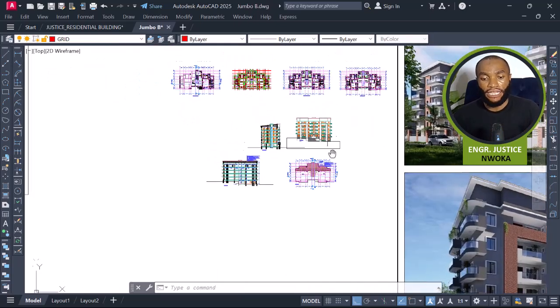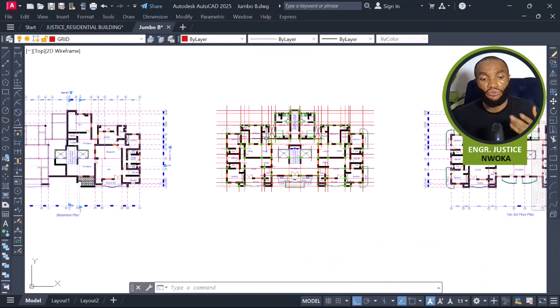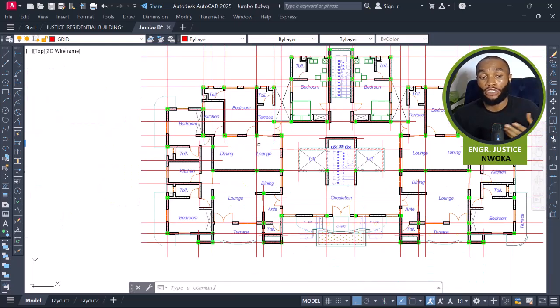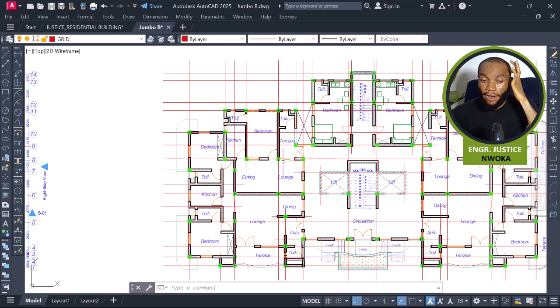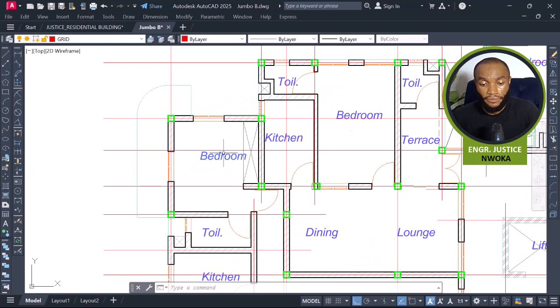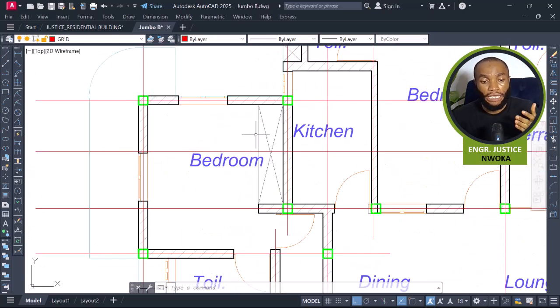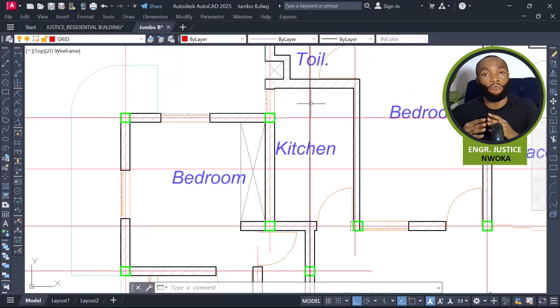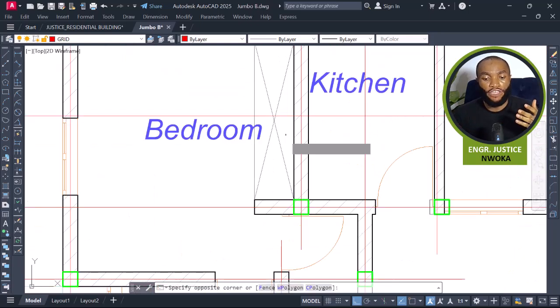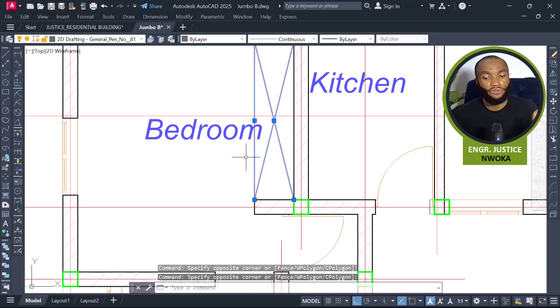So with this, let's begin with what we have today, which is the structural paneling. Now, paneling simply means what? Trying to arrange your beams and your slab, to look at the slab and try to collapse each of these panels to make up one or two panels. So we are going to be removing everything that is not necessary for this building.